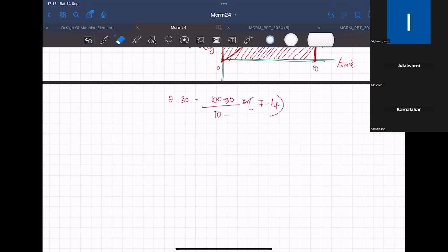Okay, so straight line interpolation. We'll go through that. Question 7: straight line interpolation has constant velocity throughout, from the start of the interpolation to the end of the interpolation. So yes, that is true. One is true. And straight line interpolation has constant non-zero acceleration throughout, but with an instantaneous infinite acceleration at the beginning and at the end of the path segment.